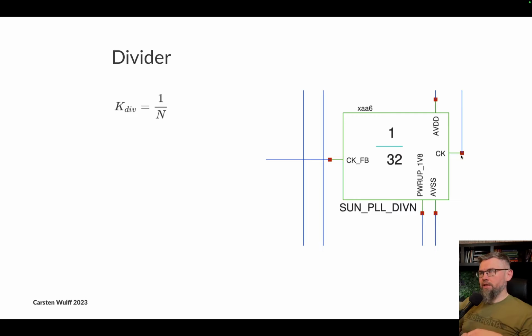Now, interesting question is, in Bluetooth, for example, we have to generate 2400 megahertz, but we also have to generate 2402 because that's the first advertiser channel. Actually, we don't use 2400, but we need to use 2402 and 2404. Now, if you want to divide 2400 and get a number that is 16, I think that is 150. But what is it for 2402? Well, it's definitely not an integer.